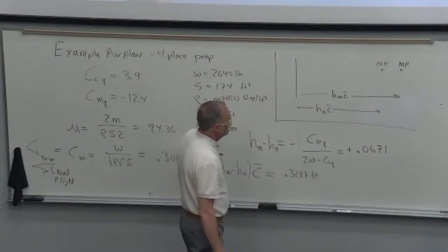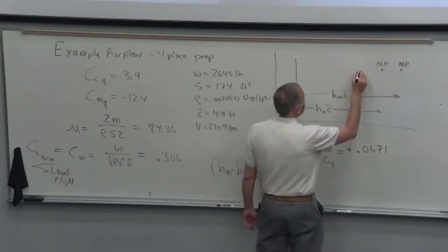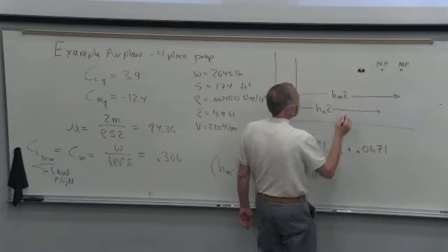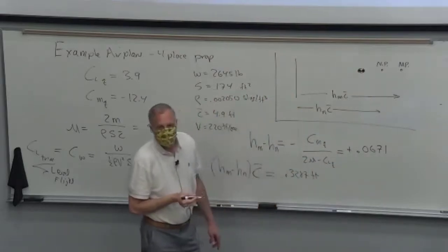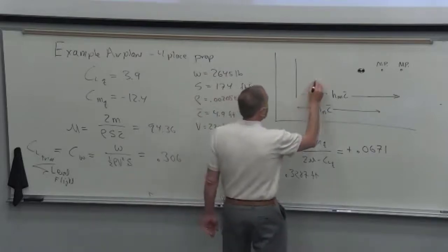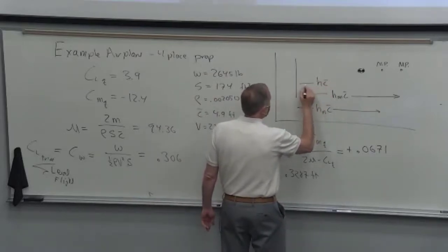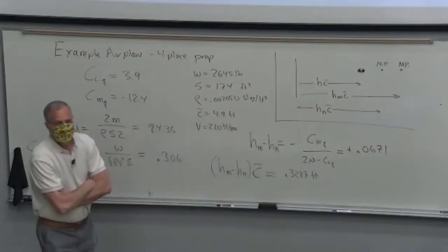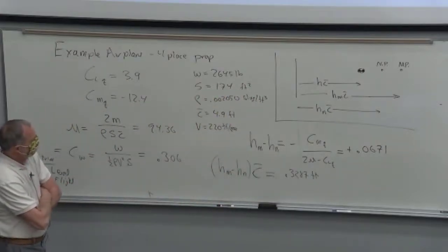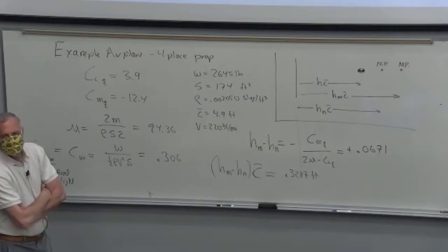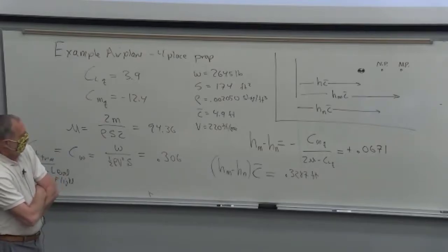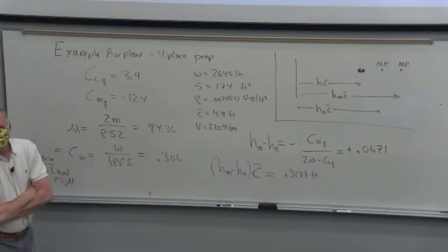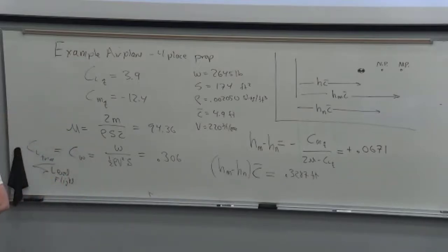And then for this airplane, when we had the CG location, it was given, it's specified. We don't automatically know just from looking at the airplane where the CG is. You have to calculate it. And so when we were doing this example before, the CG was indeed in front of the neutral point. And for this airplane, the maneuver point is behind the neutral point. For most conventional aircraft, that's true, but we still need to calculate.